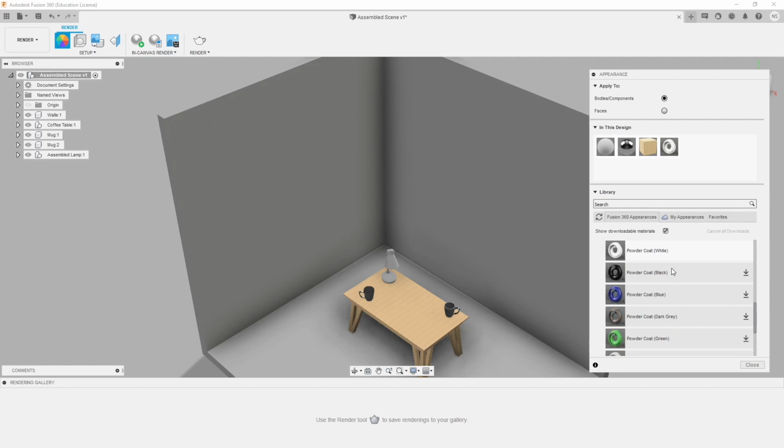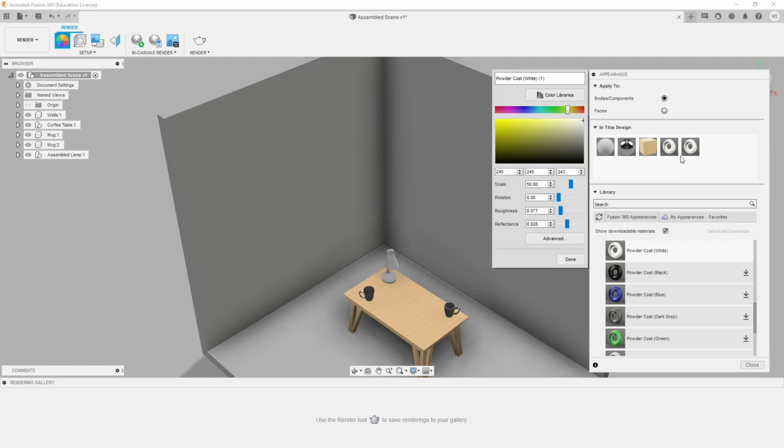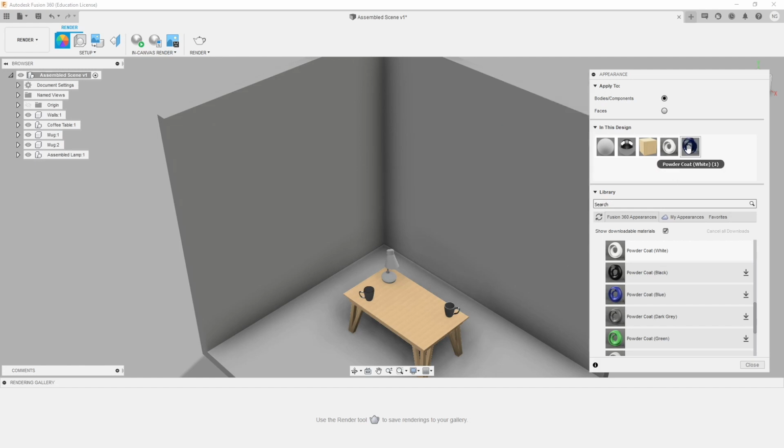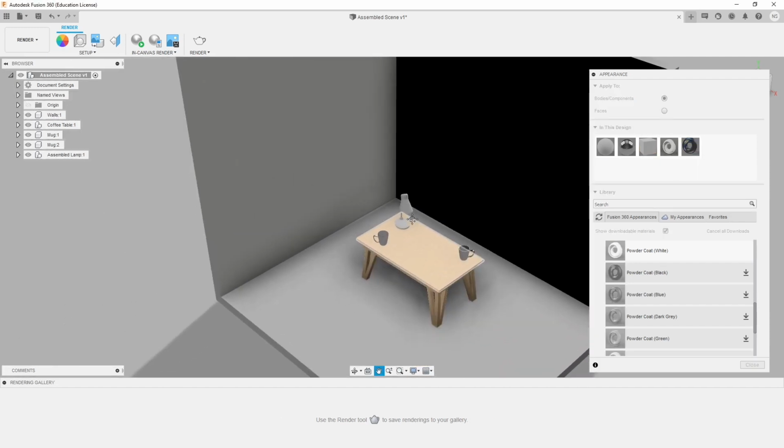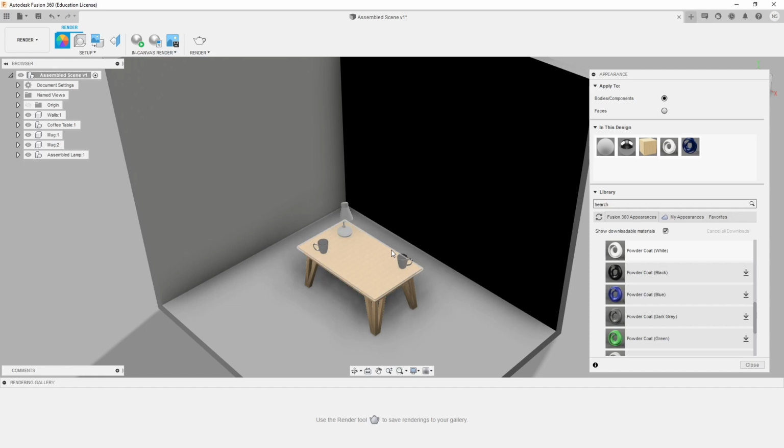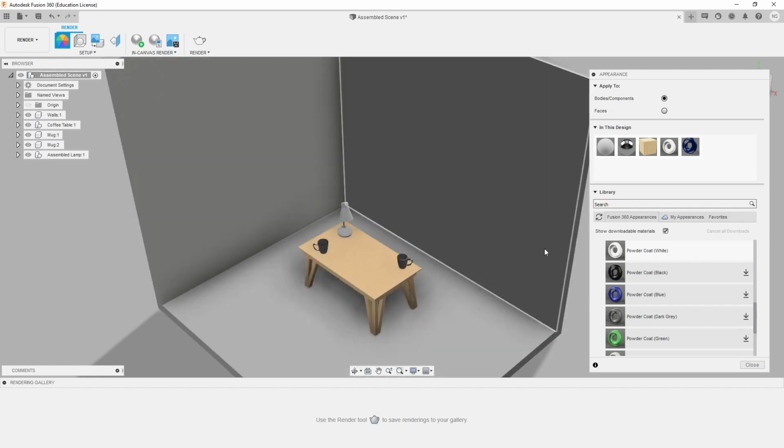Now these colours might not be what you want them to be, so what you can do is right click and duplicate it, right click and edit, and then you can start playing about with the colours that you see. So I'm going to go for navy, or a very dark blue this time. Okay, so once you've got what you want, click OK, it'll give you a bit of a preview of it. Click the surface again, drag and drop the material on. Okay, it doesn't look very dark here, but once we render it, I'm sure that will change.